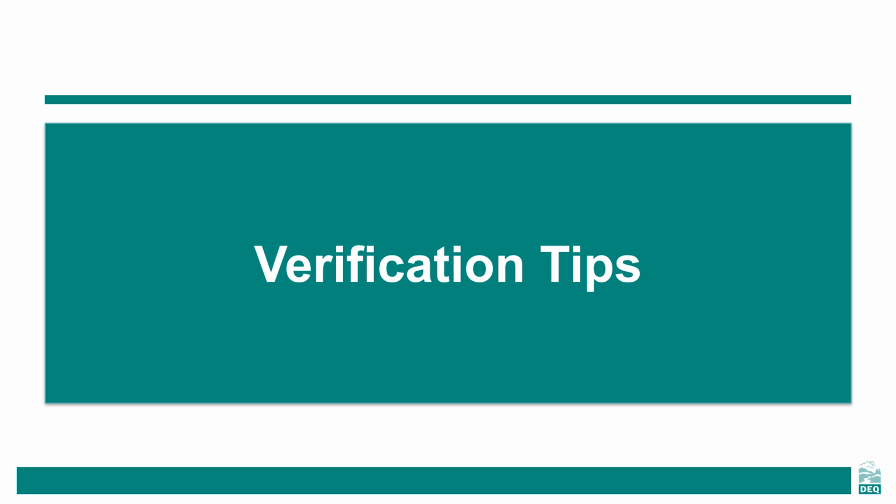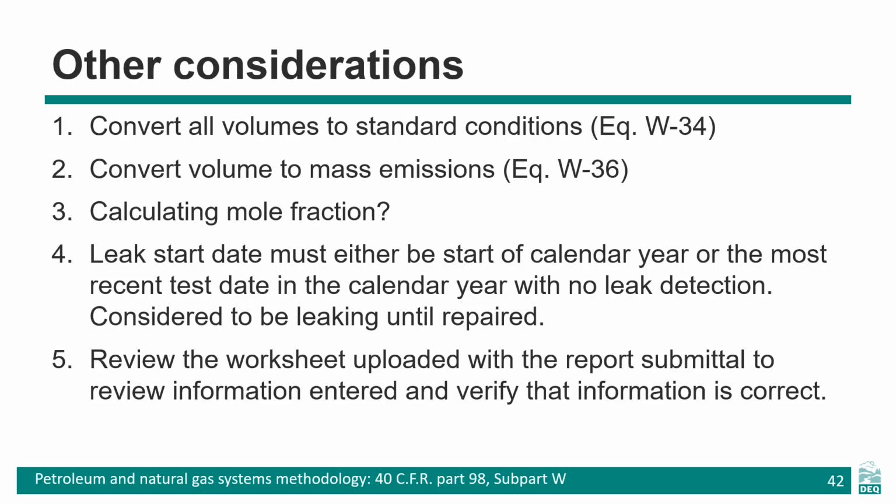Let's cover some tips for successful verification of this sector. Make sure that reported volumes have been converted to standard conditions. Things like blowdown emissions will have gas under pressure and need to be properly converted.